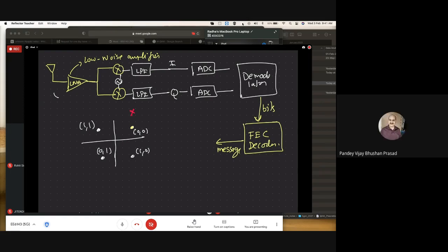Sir, I just want to ask: on the receiver side, in your demodulator, where the oscillator is, you don't have the phase shift of 90 degrees here. Yes, one of them, I have it. I'm not drawing that here. What you said is absolutely true. There's a sine wave that goes here, and there's a 90-degree phase shift. Thank you. You are absolutely right. I just didn't draw that. I was a little bit lazy.